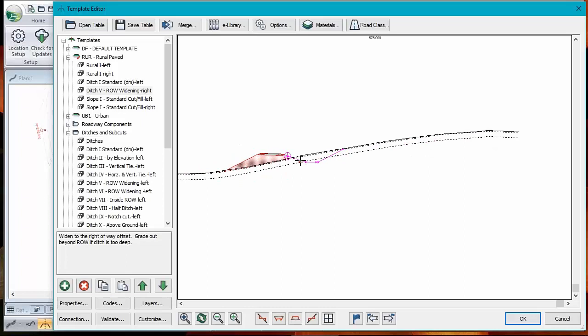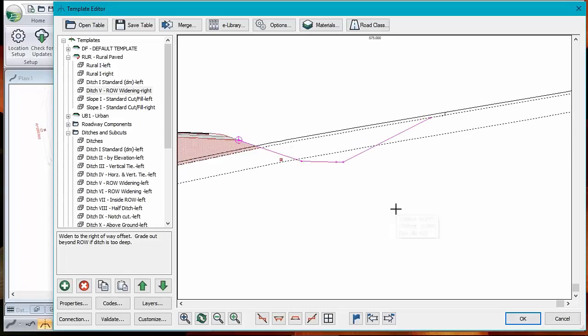Yeah, it makes the bottom of the ditch wider. Look at that. Okay, so this template sort of does that. Look at the bottom of the ditch here. There's this extra leg in here. As I lift the component up, it actually makes the ditch wider so that the daylight is always at 35. So that might be exactly the component that you want.